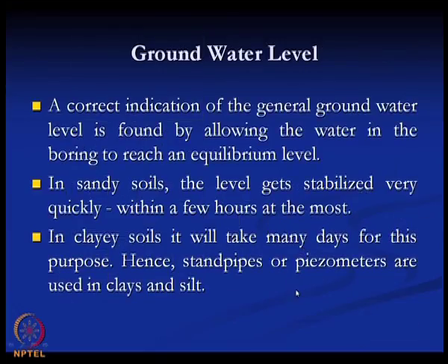The next one is that we should know the location of the water table also. As I mentioned, the location of the water table is a very important issue, because as the position of the water table changes, the load carrying capacity of the foundation or the soil, and the settlement of the soil, will also change.